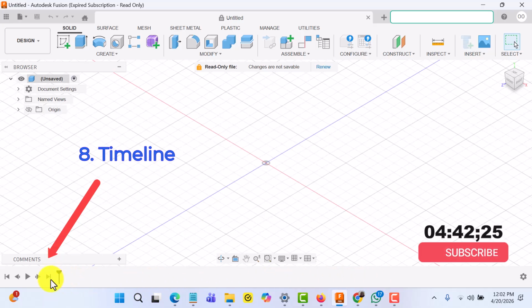It enables parametric modeling. So in case you make a mistake in your design and you realize it at the end of the design, with the help of the timeline, you can go back to that stage of the design and make the necessary edits. This is like the history of your design. You can go back and change anything, even after many steps, using the timeline.